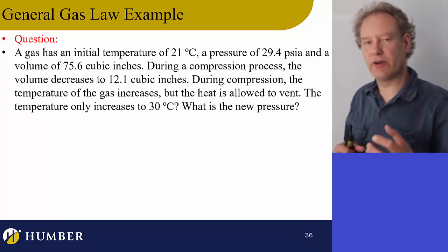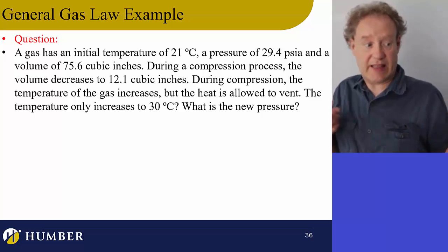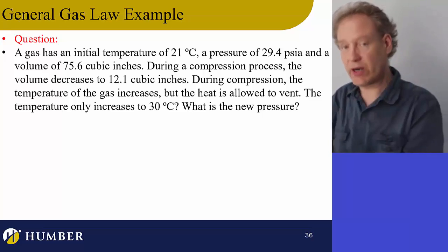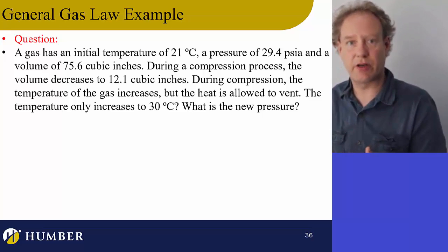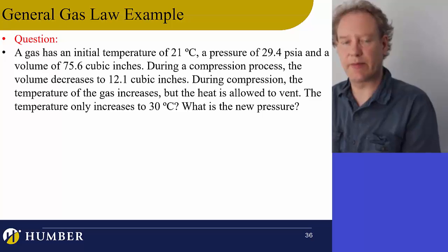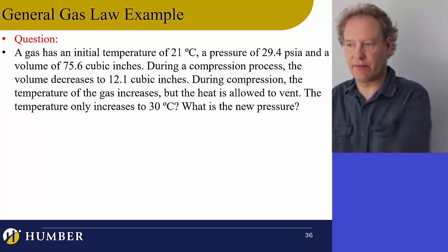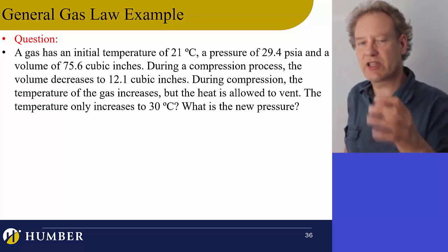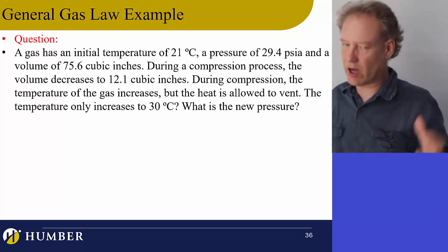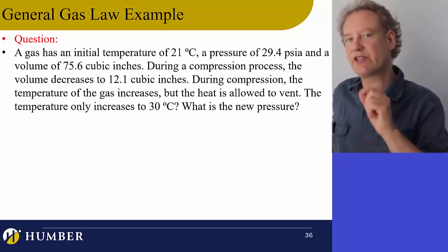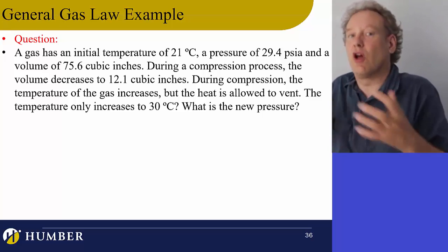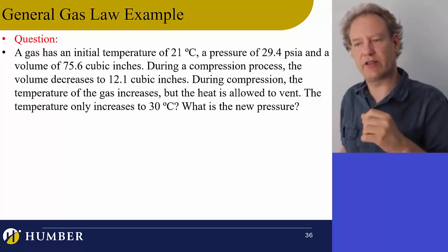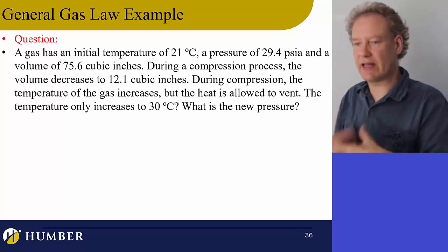So what I want to do is take the air coming into the compressor, compress it, take all of the heat out of it, and then put it into my vessel at the same temperature. Because it's going to end up being the same temperature as it came into the compressor within a certain amount of time, because all that heat will dissipate. So the process of compressing, really, we want to take a lot of that heat out. Although, when I say a lot of the heat, we don't take all of the heat out. We could, but it's really costly. So we just do as much as we can to take the heat out.